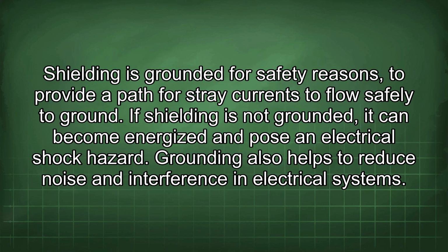Shielding is grounded for safety reasons to provide a path for stray currents to flow safely to ground. If shielding is not grounded, it can become energized and pose an electrical shock hazard. Grounding also helps to reduce noise and interference in electrical systems.